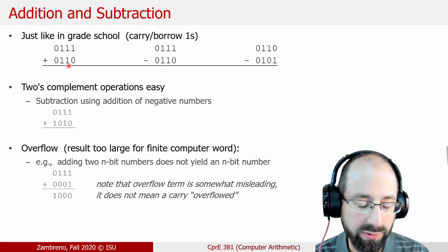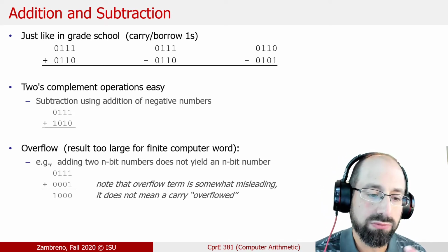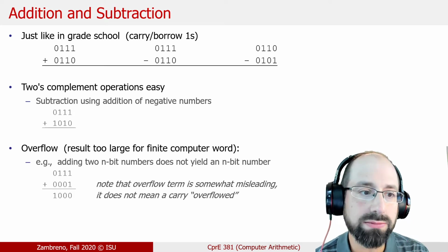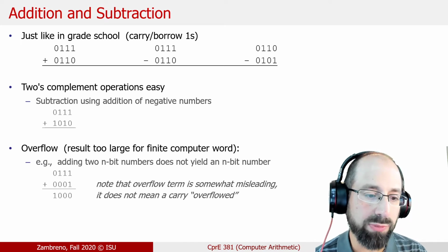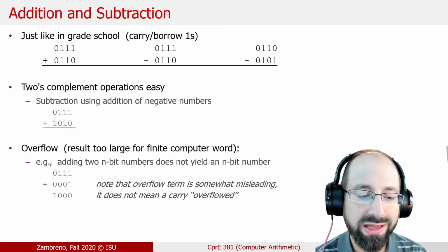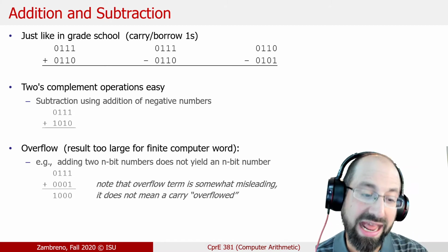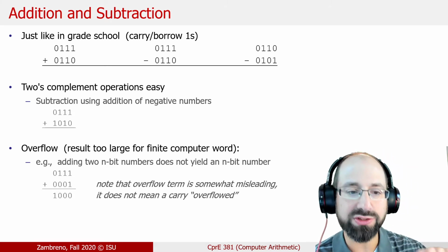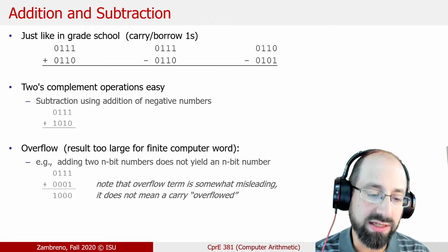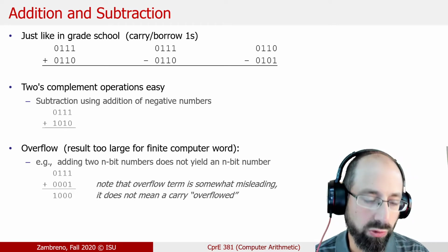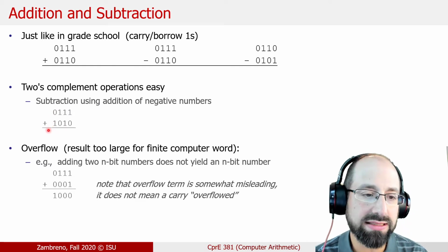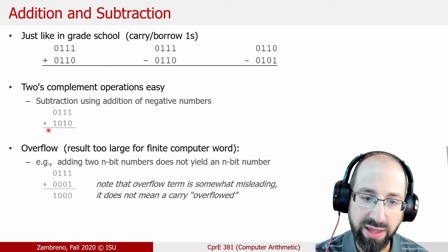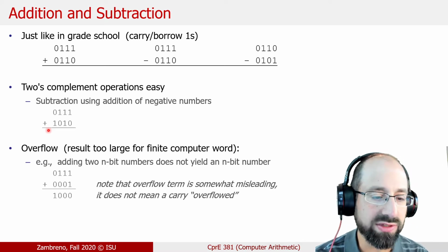And we've covered, even from a very early week in the semester, that if we want to handle subtraction, one approach is just to treat that subtraction as addition of the equivalent negative number. So there's that inversion, or that complement, we take of the B input to our ALU, and we're doing that so that we can still use what's effectively an adder circuit and not have a separate adder versus a subtractor circuit, and treat everything as if it's an addition. We just then have to be a lot more conscious of what our sign bit is doing, and understanding that now, if we have that two's complement representation, that most significant bit has special meaning. It represents the negative power of 2 of that MSB, versus just an entirely unsigned representation.